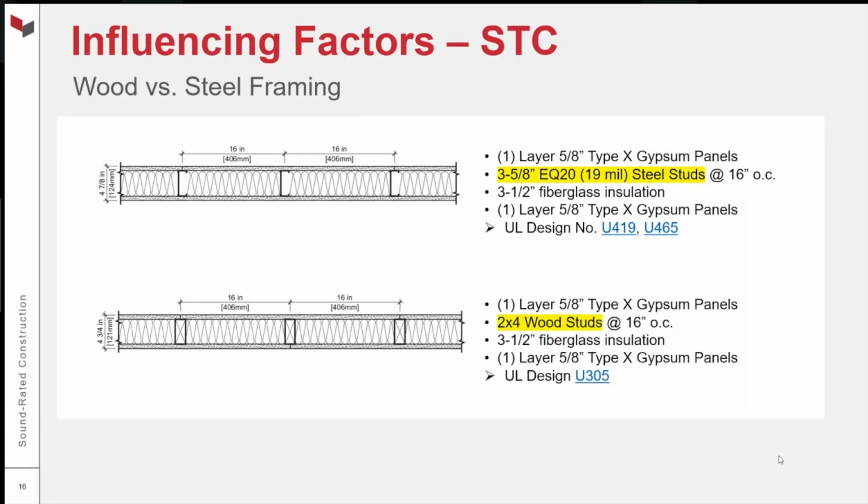So I'm going to show the UL designs in these upcoming slides, and it's really important to defer to those designs when it comes to the details, fasteners, fastener spacing, what is and isn't allowed in these various designs from a fire resistance standpoint.